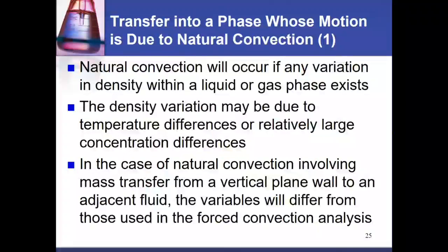So this is natural convection. You carry the whole phase, not just the solute. In diffusion, if you remember in chapter 22, we said just the component, the solute, transfers. If you have air at uniform temperature and uniform pressure, and at a certain location it contains water vapor, the water vapor will diffuse in the stagnant air to other locations.